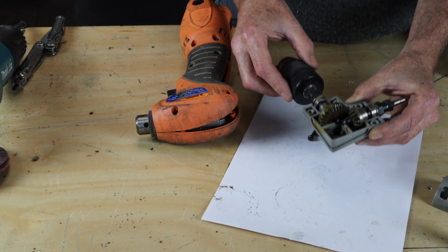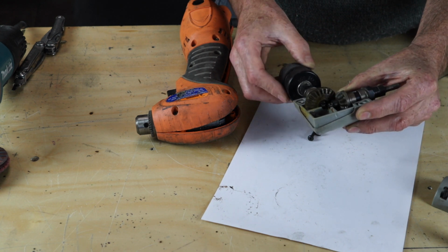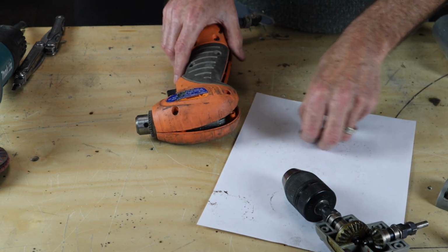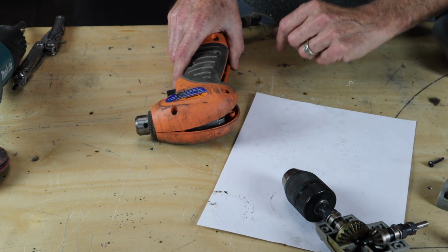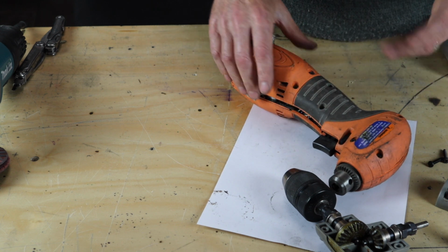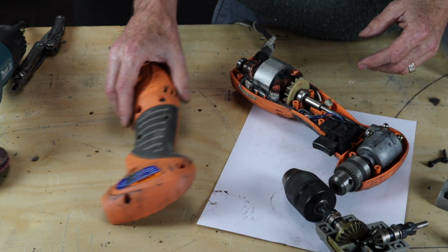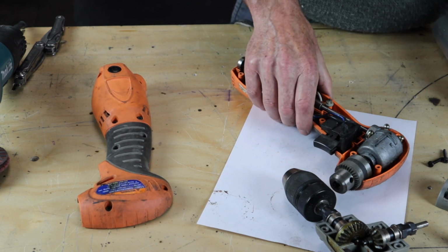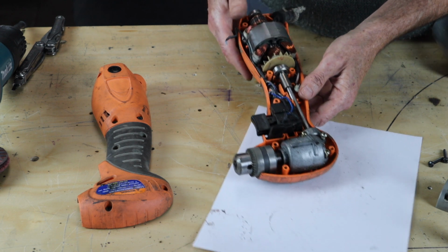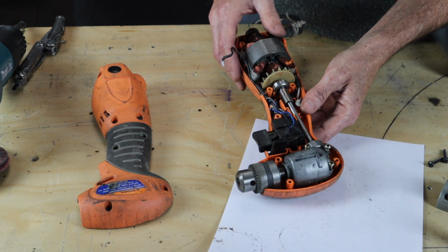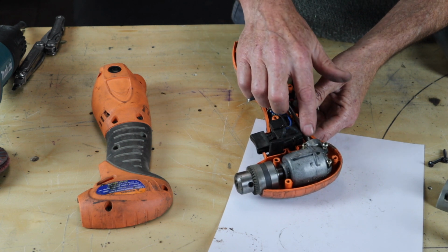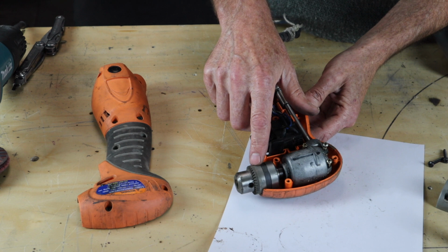And these are very simple bevel cut gears and give you a nice 90 degree, reasonably efficient, fairly cheap version. If you want to go a little bit fancier, this is a right-angled drill, not quite right angled, but very close to it, that I managed to destroy quite effectively. And if we look inside, you can see there's the motor down here in the handle where all the weight is. The motion gets transferred up this shaft into a right-angled gearbox and then to the chuck.